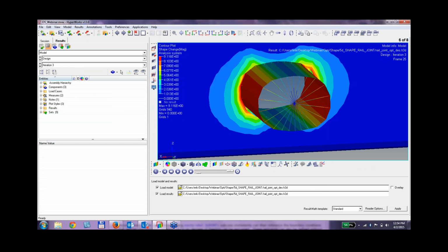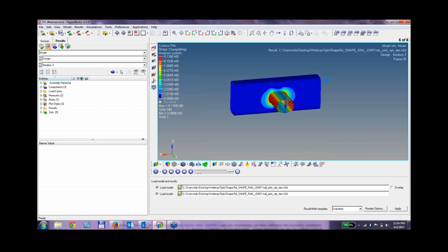It will save this shape in a grid form, or as elements and nodes, and that can then be brought back into HyperMesh. And we can use a tool in HyperMesh called OSSmooth, or we can just directly create surfaces from the finite element model, or from the finite elements themselves. So we can ultimately bring that back into a CAD system.